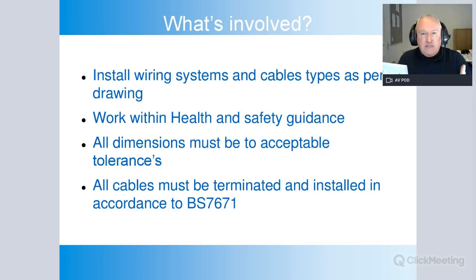If it says 400 millimeters from a wall, it's got to be 400 millimeters. You can't decide to do it 420. And again, if you don't do that, you'll fail the assessment.